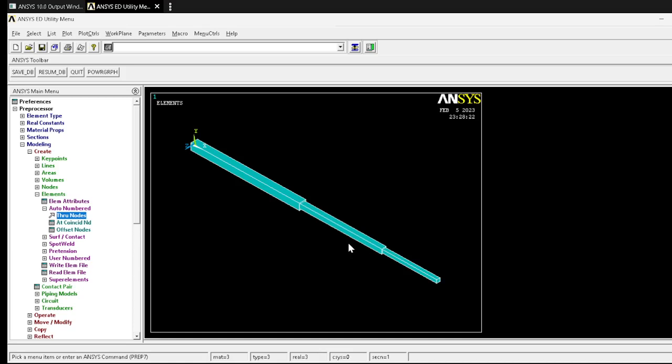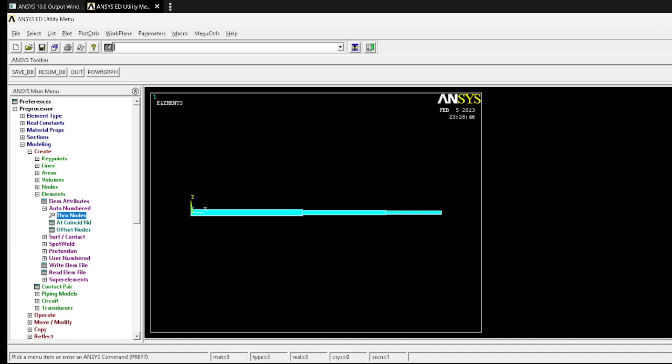So now if we do like this, we can verify again correctly the material, that is element attributes, or not. Suppose this is looking the same area, means we are not given properly. Maybe you have not selected the element attributes. This is very important. So let me remove this again, keep this in front view.